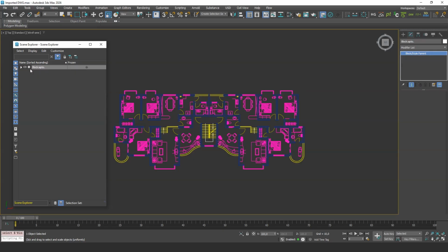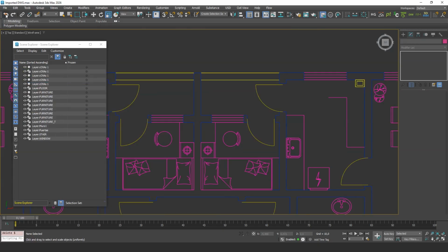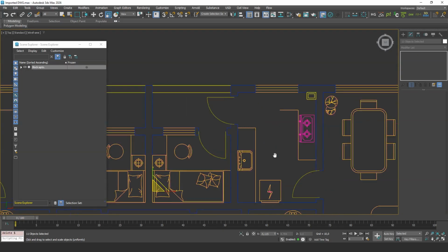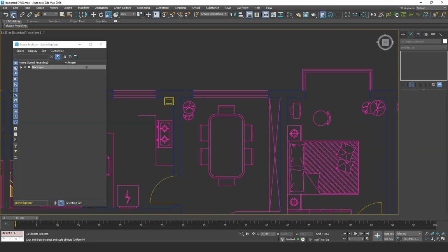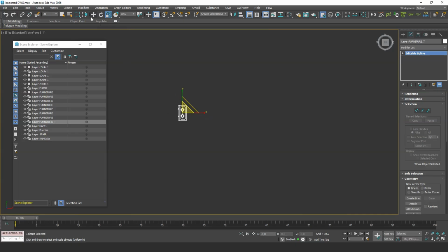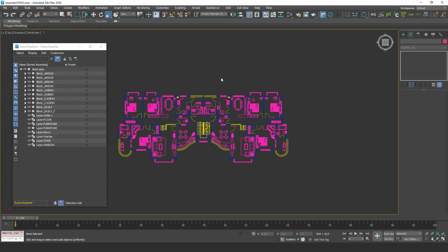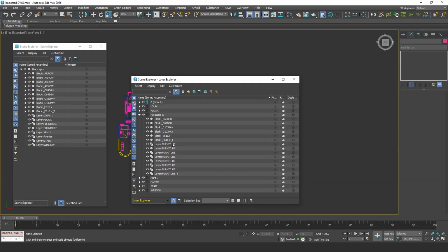Scenes imported from CAD often contain technical elements that are not useful for ArchViz. They can also introduce hidden problems that may affect the scene later. Because child objects inherit transforms from their parents, these issues can propagate through the hierarchy and cause unexpected behavior. There are also other common problems in imported scenes, such as unwanted layers and duplicate object names.